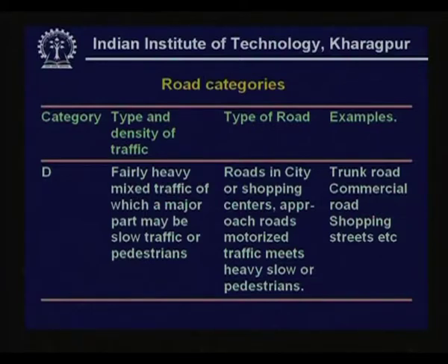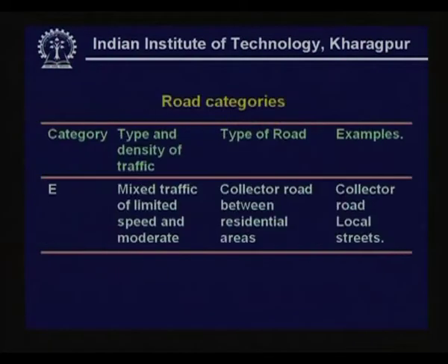They are called category D. Now, why are we looking at this? When we look at any of the standards for the official recommendation levels, the two issues which come up are the luminance levels and the visual uniformity indices, and they depend on the category of the road.